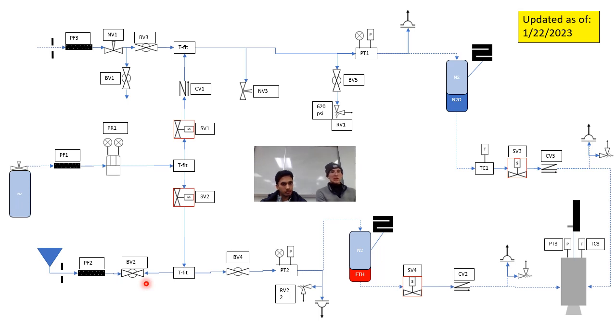You might want to pressurize it a little bit more, so maybe increase the pressure regulator at that point to, again, 15 psi. We just want to make sure it doesn't leak down to the point where atmosphere can come back in. So I'll make a note of that.